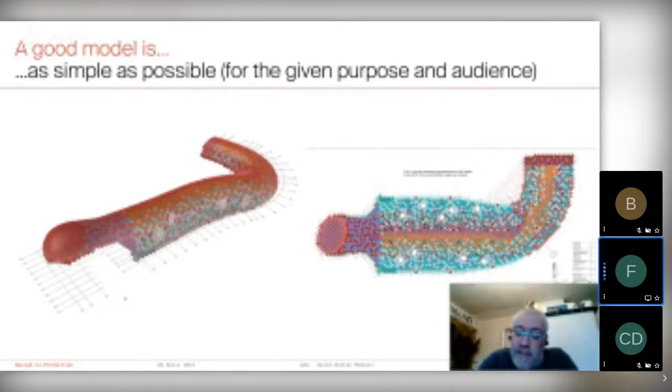But it's more than a drawing. It's really a model. So the two models actually correspond with each other, and changes in one model are reflected in the other model and vice versa. So we could put the right-hand model on the table basically in meetings and coordinate with the facade engineer, with the MEP engineer and all the others, what we would do and how we would shift element types back and forth.